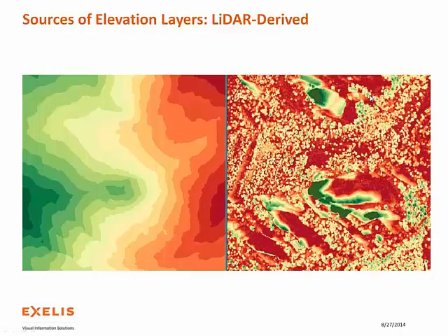And one of the things you can do once you have the bare earth and the surface information is create something called a height model. The foresters call it a canopy height model. It's called a lot of different things, but it's the same thing: you subtract the DEM from the surface model and you're left with elevation features. So you can start to learn about the heights of things, or even the changes of the heights over time. So say you're doing any sort of pipeline analysis and you want to see if there's been any movement, the height model over time would be something you could use in an easy comparison.